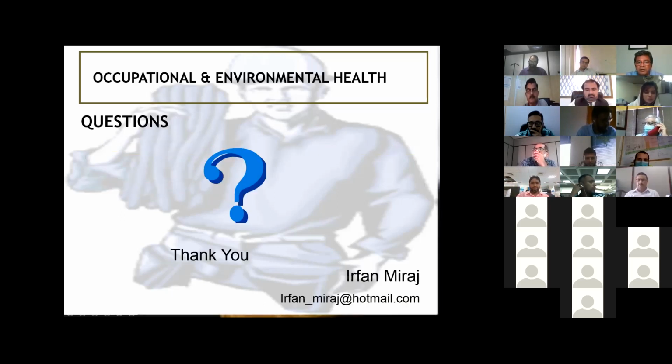This ACGIH also issues a booklet every year, which contains the TLVs, the threshold limit values for all the contaminants. Threshold limit value, people would know, is the maximum value to which a worker can be exposed for 8 hours, 5 days a week. So they issue a booklet of every chemical, every contaminant. That's a good guideline. For members, it's free. Yeah. So I think that is the end.